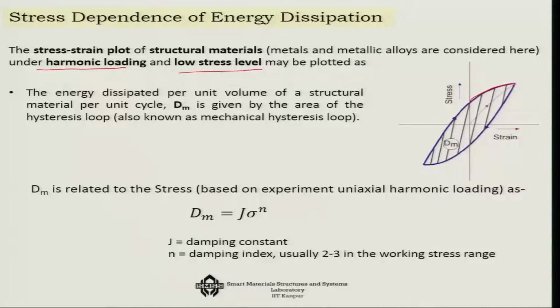It starts from here, and with the reversal of stress, the strain comes back, but there is some plastic strain here. You reverse it further, then it goes to the other side, and this cycle continues on and on. The area under it is the energy that is dissipated due to hysteresis, as we call it. The reason for hysteresis could be all of those kinds of internal dissipation taking place inside the system.